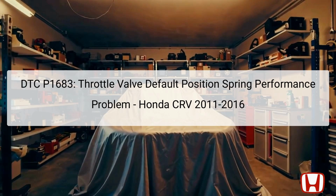This presentation focuses on the DTC P1683, which indicates a throttle valve default position spring performance problem in Honda CRV models from 2011 to 2016. The throttle body is a crucial component of a vehicle's air intake system, responsible for regulating the amount of air that enters the engine. In the event of a malfunction in the throttle valve spring position, the engine's performance can be compromised, leading to potential drivability issues.